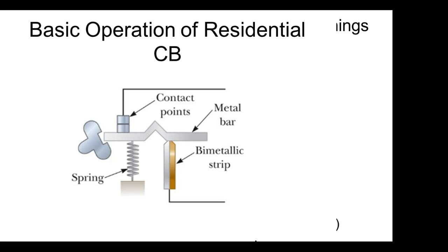So this is pretty much the way it is. What would happen is the bimetallic strip would heat up and do what? It has to move over, and the spring's trying to do what? Break contact. The bimetallic strip is in this thing right here. It won't come back out, right? You understand that? Until you do what? Until you come over here and push this thing. So normally what you have to do is go all the way off and then reset it, and then pop it over.